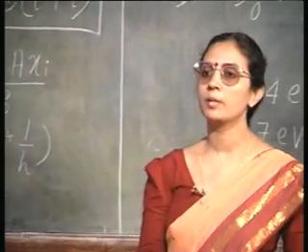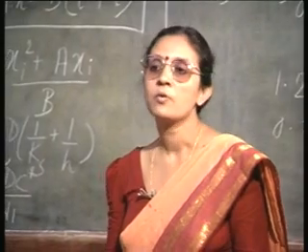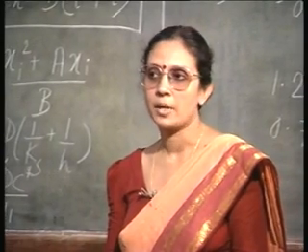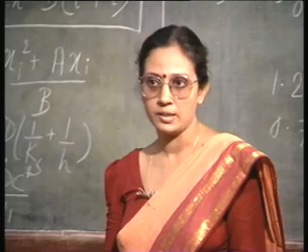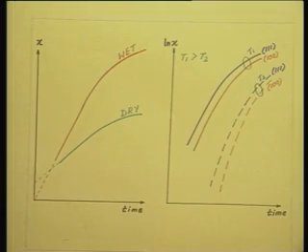The only problem starts when you are going to grow very thin oxide by dry oxidation on silicon. Very thin oxide, that is, according to Deal-Grove's model, it should have passed through the origin, but in the experimental I always find there is a non-zero intercept on the x axis.